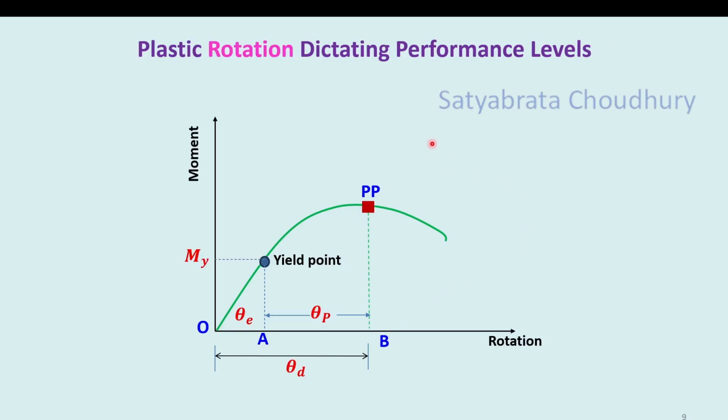Same thing we are now taking in terms of rotation, not displacement, because in most of the FEMA documents our performance levels will be dictated by rotation of the members and not displacement. So if it is rotation, the corresponding force is moment, so it is a moment-rotation response.